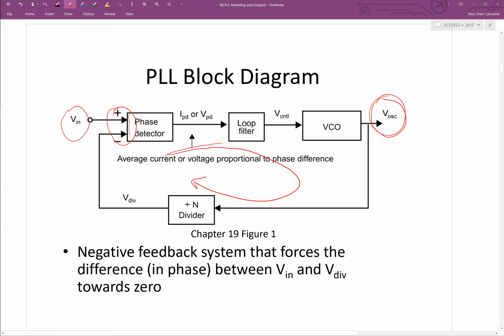So that's why the first circuit here is called a phase detector. It's comparing the phase of the clock waveform here with that of the clock waveform that's being fed back. And if there's any phase shift between them, then that's the quantity that's being produced at the output. An output is produced there proportional to that difference. That quantity is then amplified, and then we've got our negative feedback loop, so that if it's stable, that difference would be forced to zero.